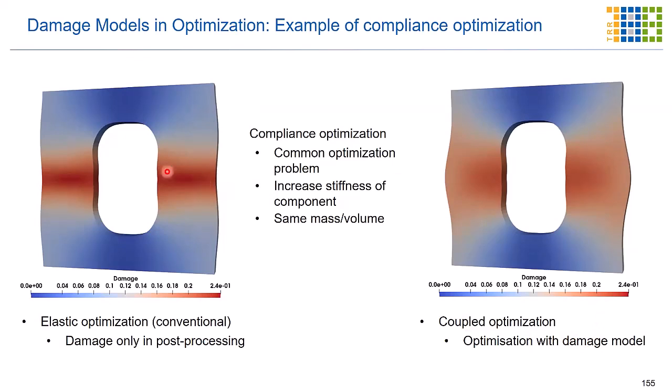Now, on the left side, that's maybe a very standard, but not very accurate approach, where you compute the elastic problem, and then afterwards you compute damage that would have evolved. On the right side, the more sophisticated approach based on the equations you have seen earlier, where the deformation updates the damage variable, and therefore always updates also the elastic moduli and the degradation, okay, during the simulation.